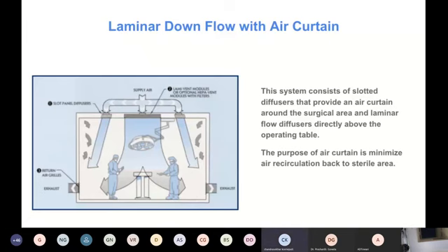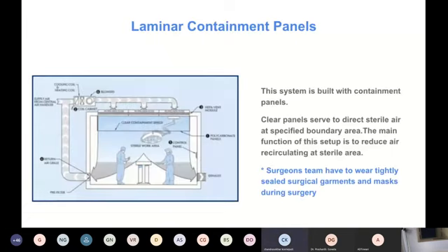The next part of it, the operation theater envelope. Envelope plays a major role. Let's talk about constructing our operation theater with puff panels. What is a puff panel? Puff panels are powder coated panels sandwiched with puff, which has a density of 40 kg per meter cube.